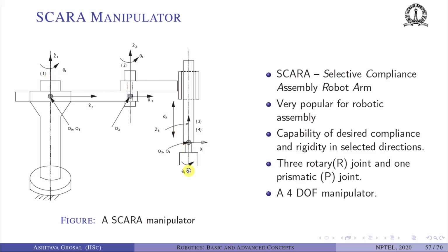So you can think of it that this robot is picking up a pin IC with pins, and then it is taken to the PCB. However, it will never be exactly aligned. So while you are trying to push it down, theta 1 and theta 2 and theta 4 will slightly adjust. Slightly means very small amount, and then it can be pushed down by using D3.